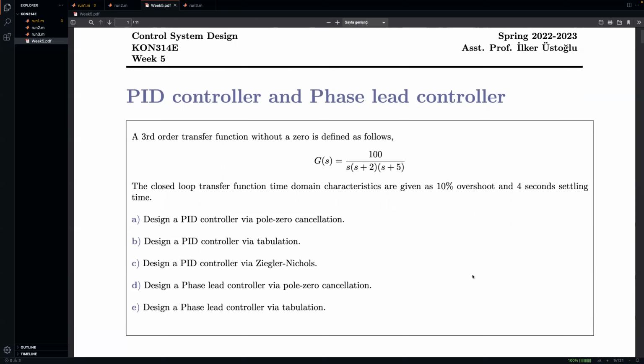But what we're trying to do is compensate the steady state value or error. So the ratio will depend upon that, but the angle contribution should be near zero. So it shouldn't change the angle because we don't want to mess up the design point that we have already established with a P-type controller or a lead controller. So a lag controller is just chosen to be maybe something around the origin, just choose one pole.